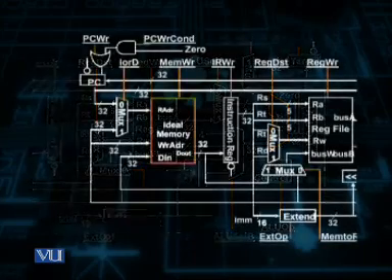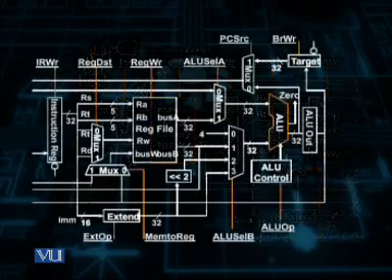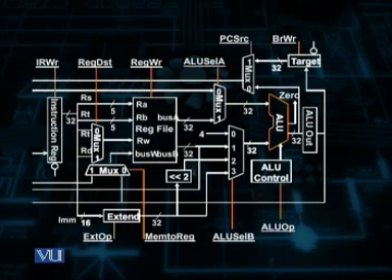As you can see from this diagram, first of all the condition test is performed, and in order to perform the condition test, ALU select A is made equal to 1 and ALU select B is made equal to 0, and the ALU operation supplied at this time is the subtract operation, because a condition is always evaluated by subtracting one operand from the other.